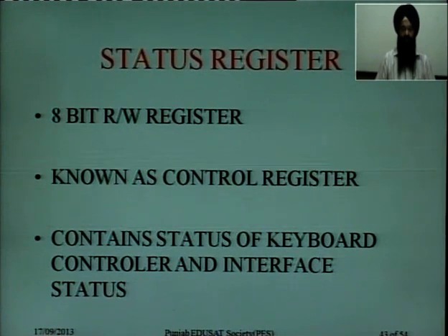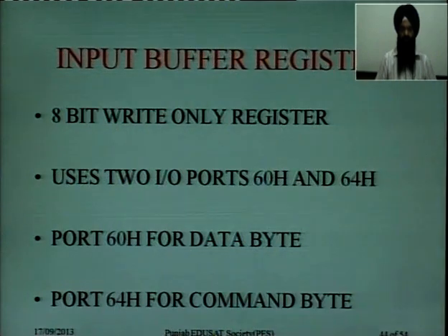The status register is an 8-bit read-write register. It is known as the control register, and it contains the status of the keyboard controller and interface status. Then the input buffer register is an 8-bit write-only register.